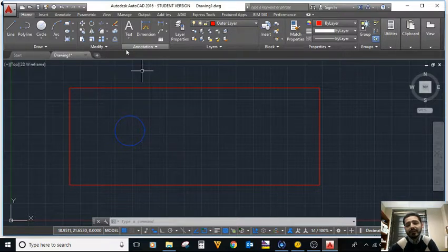If they have very sharp edges, that will make life harder in case someone is not paying attention and hits it, and it would be a hazardous situation. So to do so, there is an option in AutoCAD to do that for us. Once you create a very sharp angle, edges I mean, then AutoCAD can modify that by your definition of what's the radius of that